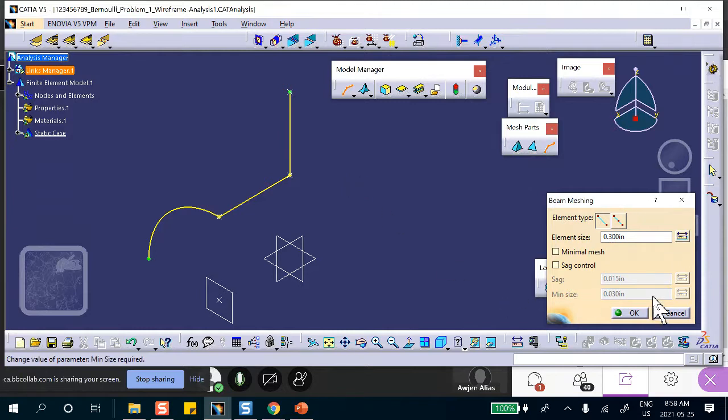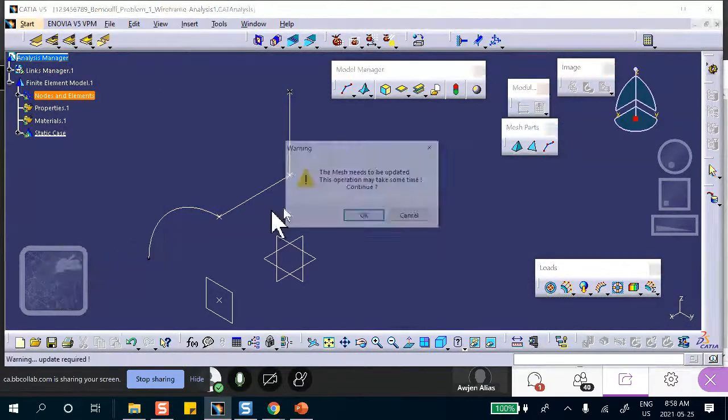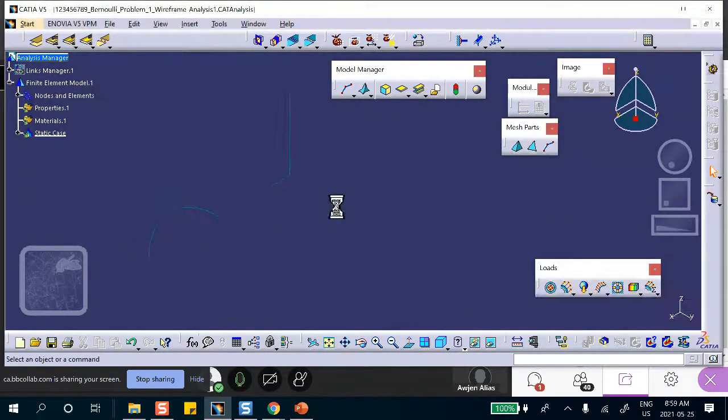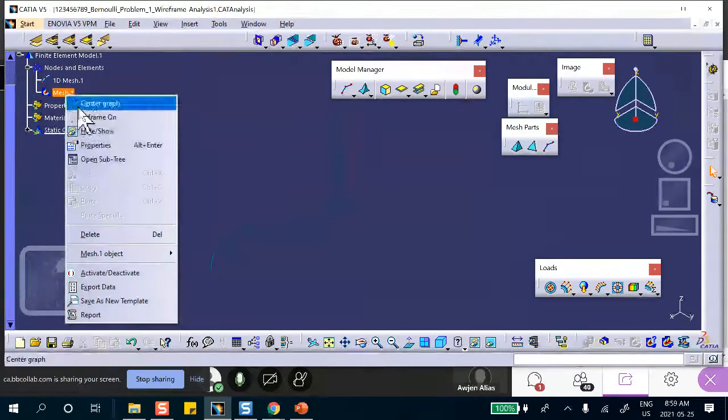Okay? Say okay. If you want to see your mesh, no problem. Mesh visualization, say okay. Let's zoom in closely to that corner, for example. Whether you come from the top element, the corner node is 30, or if you come from here, the node is 30. If these were not joined, the node on the top and the node from the side would be different. And this is why you have to create connection. We will see connections, but not for these beams. Rest of the problem, deactivate that.